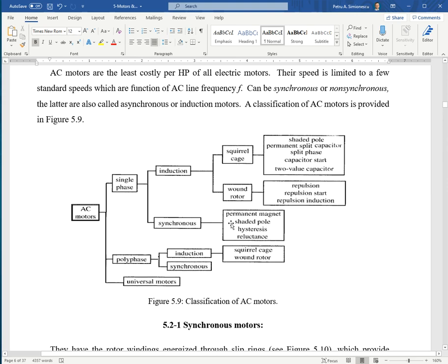And if you've noticed, sometimes the platter rotates one way, sometimes the other way. For clocks, in order to rotate the same direction, a one-way clutch is used. And then on the single phase induction motor, there are means to amplify the stall torque, so you have higher torque available at startup to break up static friction and inertia.